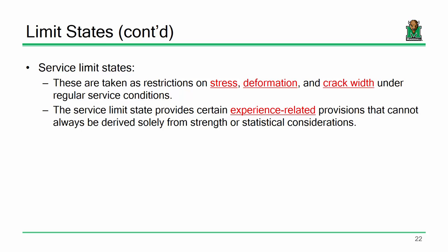One very popular one is live load deflection. We have many bridges out there that are perfectly safe to resist loads, but they're governed by the fact that they can't deflect too much. Because if you're driving down the bridge and the bridge is deflecting like this, it's not going to be a very comfortable ride for you, is it? You wouldn't like to drive on a bridge like that.